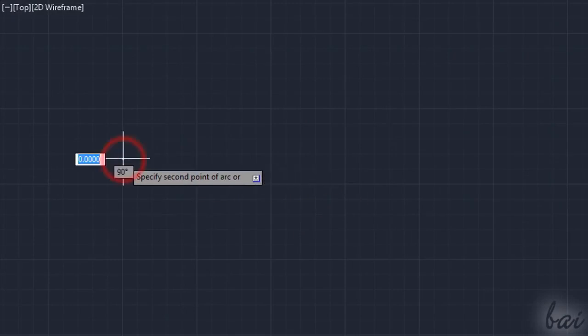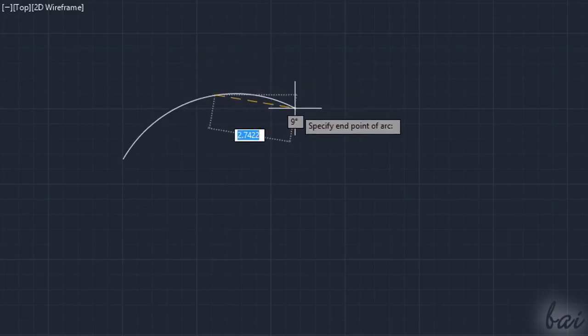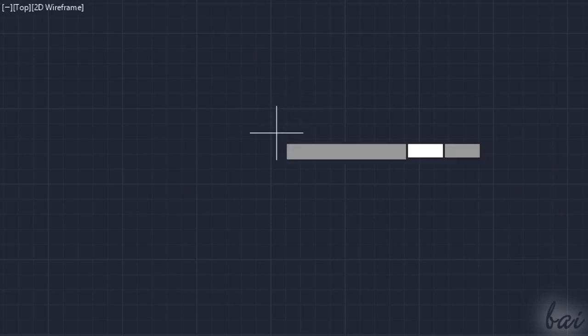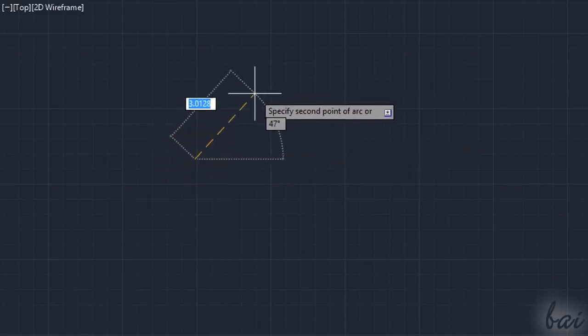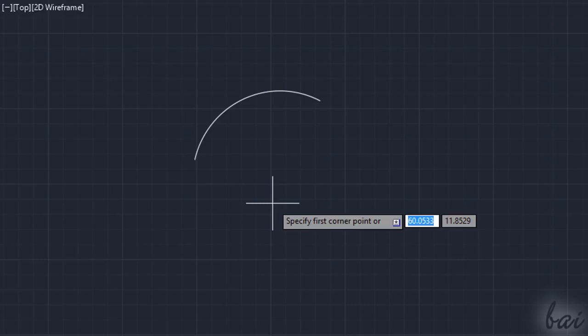While you draw, AutoCAD shows the shape of your drawing in progress. To undo all and cancel your drawing, use the Escape key. Once the object is dropped on the workspace, the Drawing tool is no more active. You can enable it back again with the Enter key. You can recall any of your latest tools used by using the up arrow key from your keyboard and applying with the Enter key.